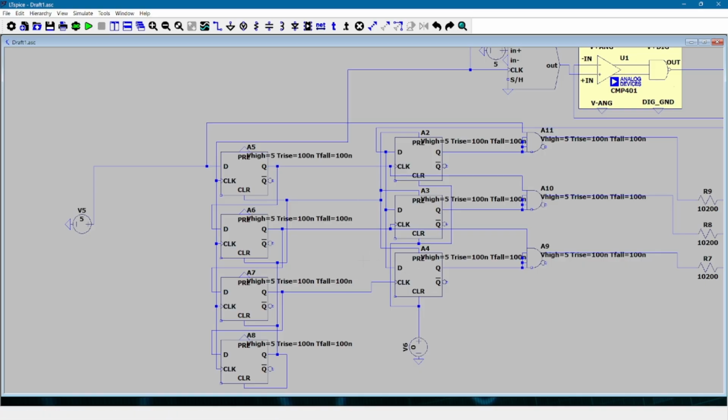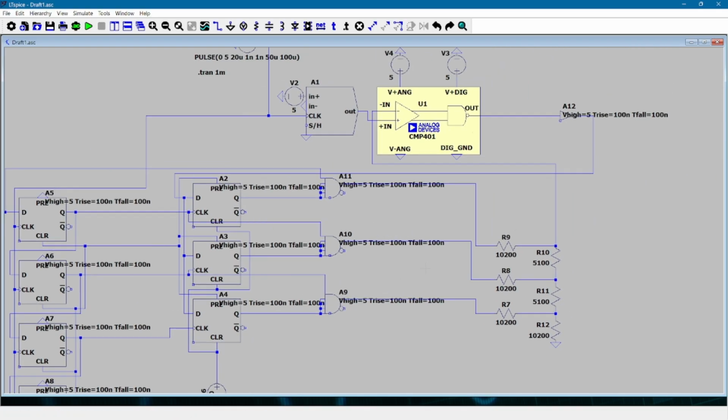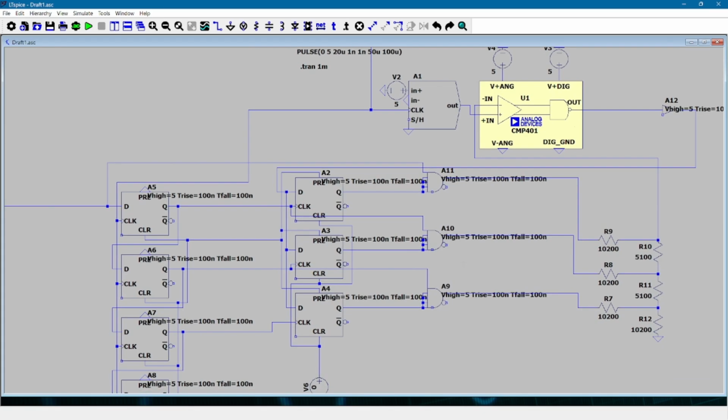And anyways, this is fed to the flip-flops, and voila, you're storing what you're finding. However, you may have a new question. How do these flip-flops even get an initial testing value? Well, the shift register, as I just discussed, can do another handy thing, which is to preload the flip-flops in sequence to test binary weighted values. You can see it tracks the MSB first.